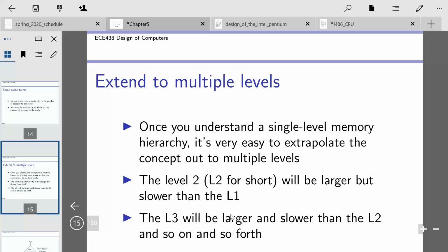The Pentium was fabricated with a newer process technology, and at that point they went split. And of course, remember they also went superscalar, and they had to then resolve the structural hazards between the two pipelines, the U and V pipeline. But the point is that at that time they were able to fit two separate caches on chip, and that was huge.